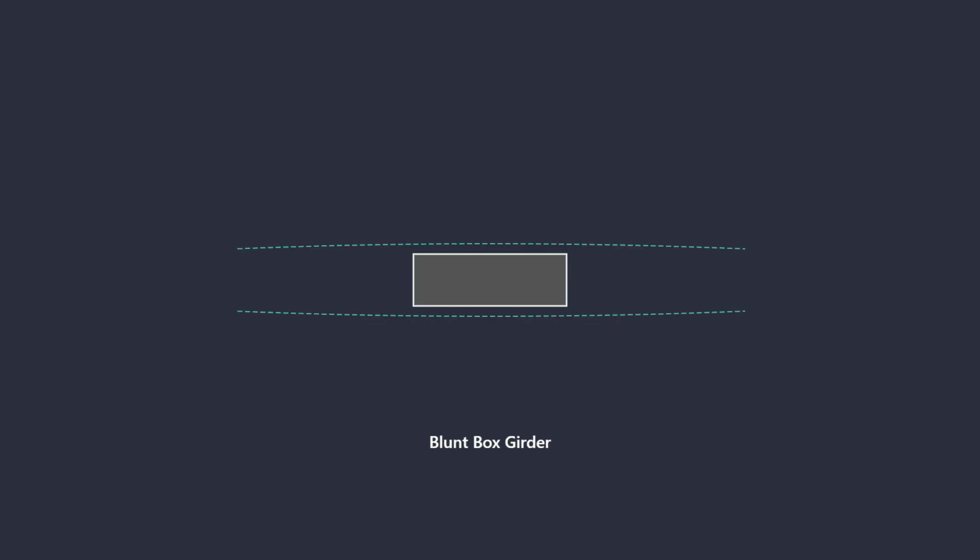Modern bridge decks utilize passive mitigation techniques to stabilize airflow and reduce aerodynamic force coefficients. Streamlined box girders are employed to minimize flow separation and suppress vortex formation, significantly lowering both drag and lift coefficients. Incorporating central slots or open gratings within the deck disrupts the coherence of the vortex shedding pattern. These openings also equalize pressure differences between the top and bottom surfaces, reducing net lift.